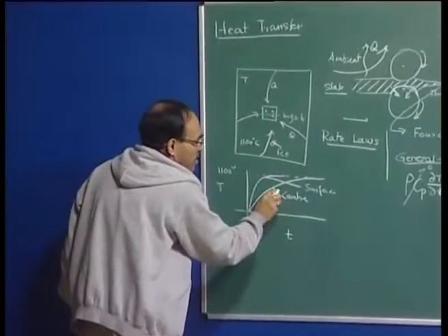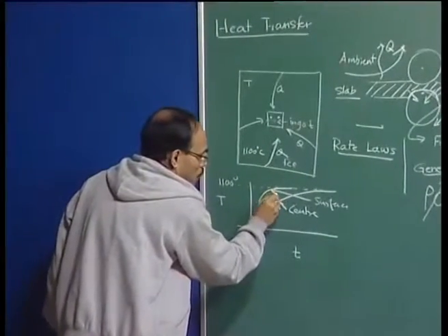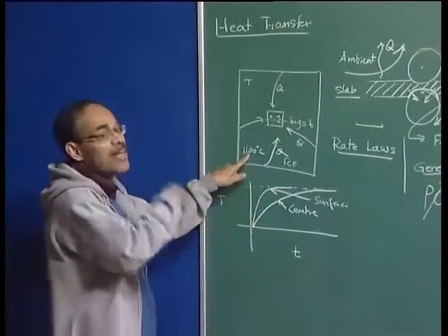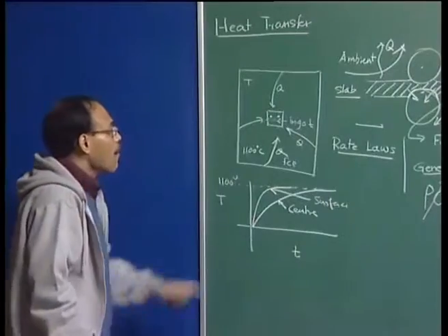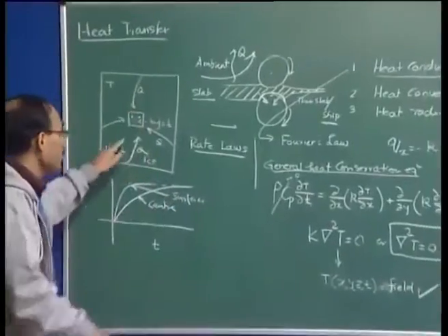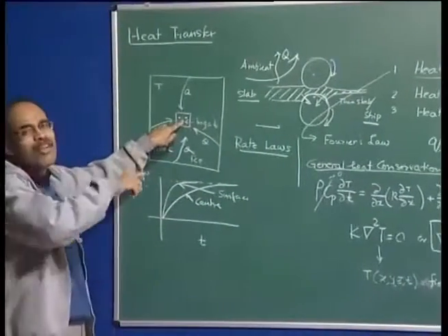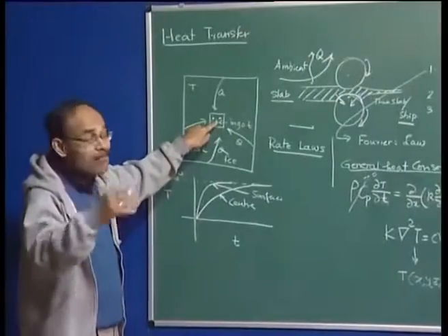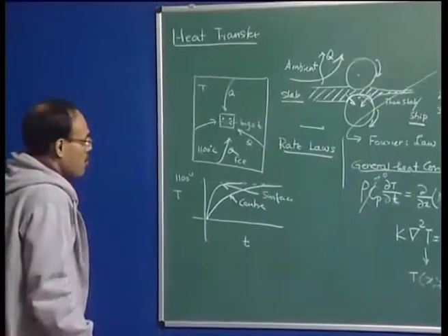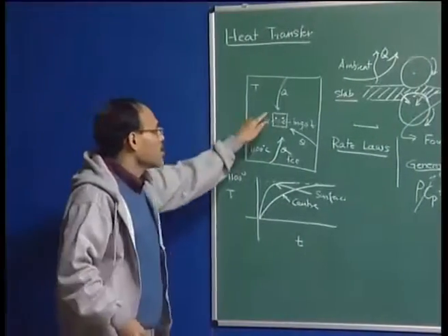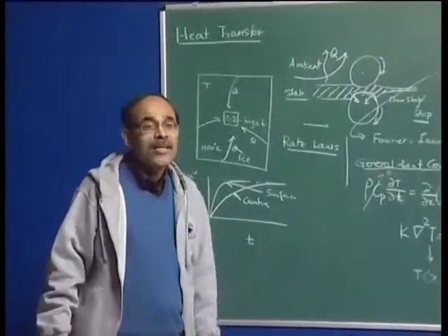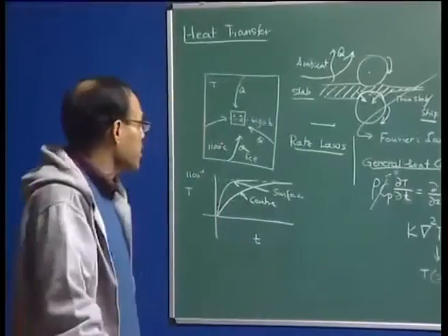So, the surface is going to attain that uniform temperature quite rapidly. On the other hand, the center is going to attain the reheat temperature, or the equilibrium furnace temperature, at a much later stage. So, having solved this equation, I will plot temperature at the center as a function of time from my numerical results, and then tell, well, after this time for such and such furnace condition I am going to get an optimum uniform temperature all through my solid, and the time required to attain that is going to be the desired or the optimum reheat time.